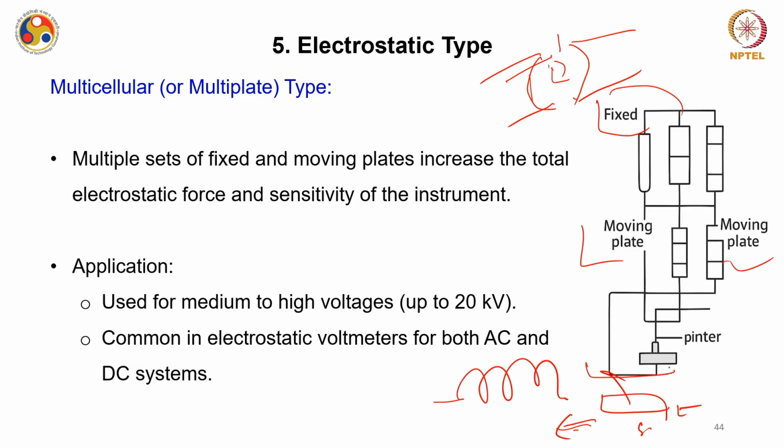In the other type, which is the repulsive type of moving iron, we have seen that because of the repulsion between these two magnets, you have movement in this pointer. That's why the first case was known as the attractive type, because you can only have attraction here. There is no repulsion. Generally, you will find that this is only attraction, because the current flowing through this coil will magnetize it.